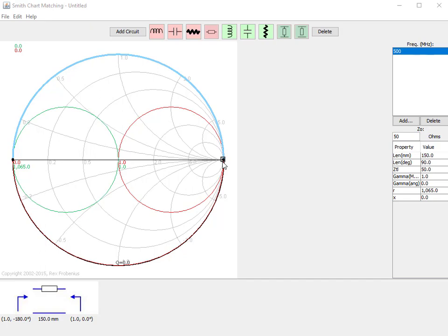So it's important to be able to predict when this would happen and adjust our circuit accordingly, either by adding more. You could add even more transmission line until you got up to a half wavelength, which when you double that becomes a full rotation of 360 degrees. That brings you back to the short. So a half wavelength just brings you right back to where you started from.